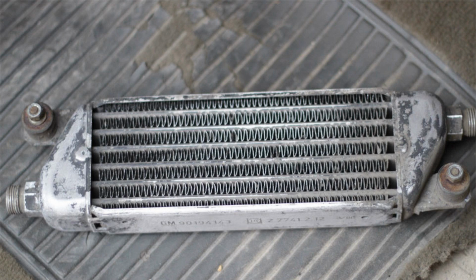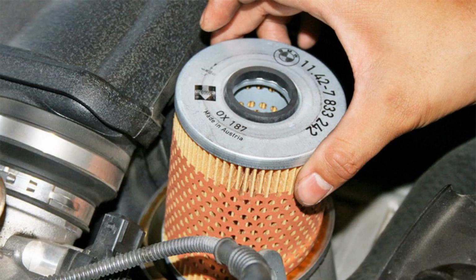Let's start with the crankcase, which is usually mentioned together with the sump. So, the sump is a part of the crankcase, located in the lowest part of the motor, and is an open container from above, into which the oil, which has fulfilled its main task, flows. Here it is cooled and settled, which is facilitated by special baffles, damping any oscillating processes arising during the movement of the vehicle. And further engine oil is directed to the oil filter.